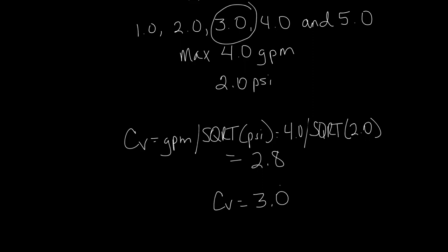Just to summarize, a properly sized valve should be quiet, provide accurate flow control, have long service life, and it shouldn't leak. Selecting a valve body for the correct CV rating is critical to making all of these things happen.